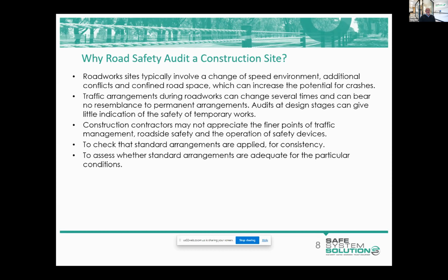And this was around practice management, that if we do rip up a section of road, at the end of the working shift, when workers are leaving site, we don't leave the site in a manner that requires it to be left at, say, 40 kilometres an hour. We actually have that loose material compacted.